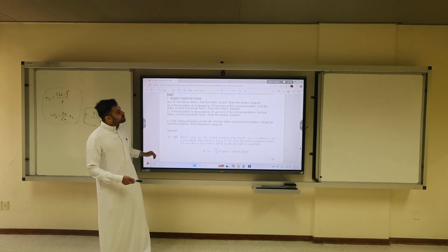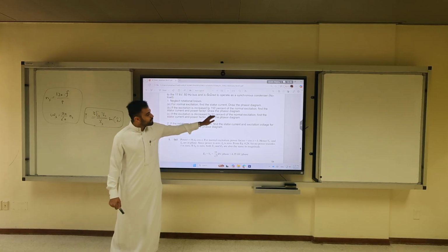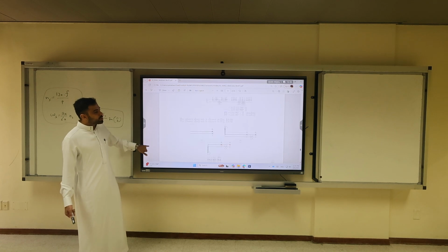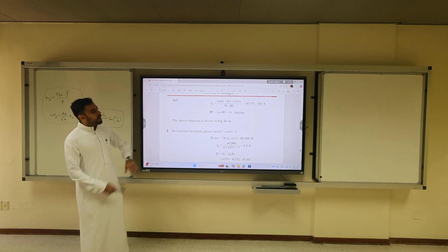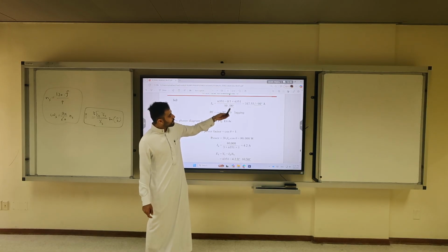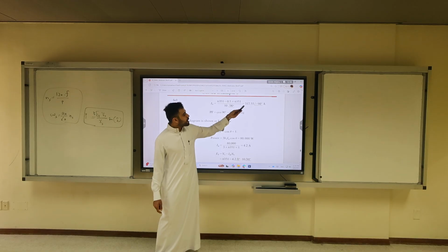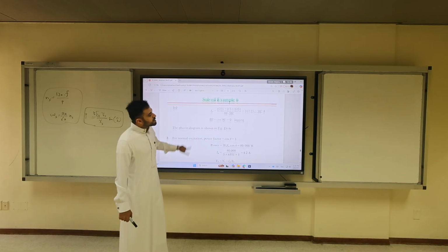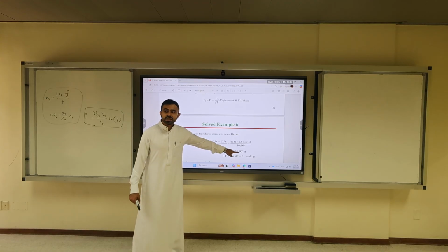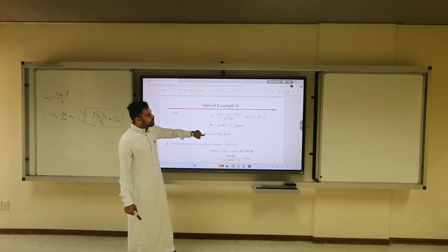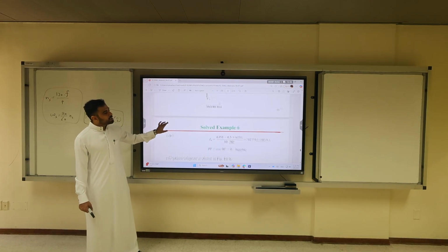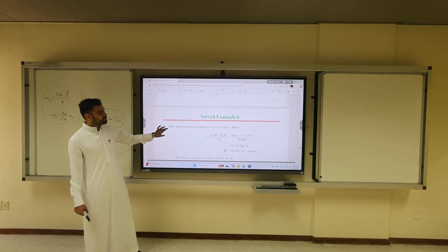The last part is if it's decreased by 50%. Again, torque angle is 0. Because torque angle is 0, I repeat everything here: 6351 minus 0.5 times that, over that. I now get Ia to be 3175.5. It's the same magnitude, if you note, 3175.5, but one is plus 90, one is minus 90 degrees. So again, parts A, B, and C, because we neglect rotational losses.